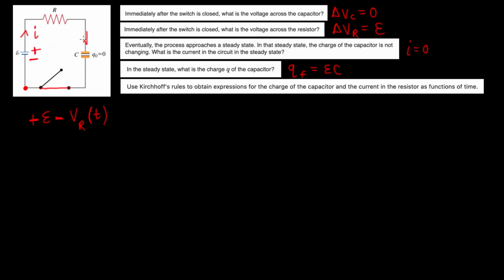And so now we're done with the resistor. Now let's go into the capacitor. And since we're going clockwise, we now encounter the capacitor, and so there's going to be a negative potential drop across the capacitor as well. And then all of that is equal to 0, because after the capacitor, there's no more elements. We just return back to our original starting point. So this is Kirchhoff's loop rule. And so let's expand this out a little further.